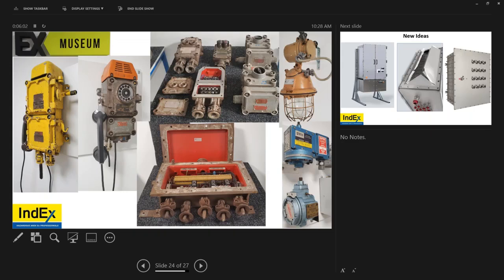We had empty enclosures. We drilled the boxes. We put the terminals inside of it. But it told us how many holes we were allowed to drill, of NPT thread, with what type of drill press, and how to thread it, and how many terminals we were allowed to put into it. Is it dangerous? Yeah, I prefer the IECEx system fully.